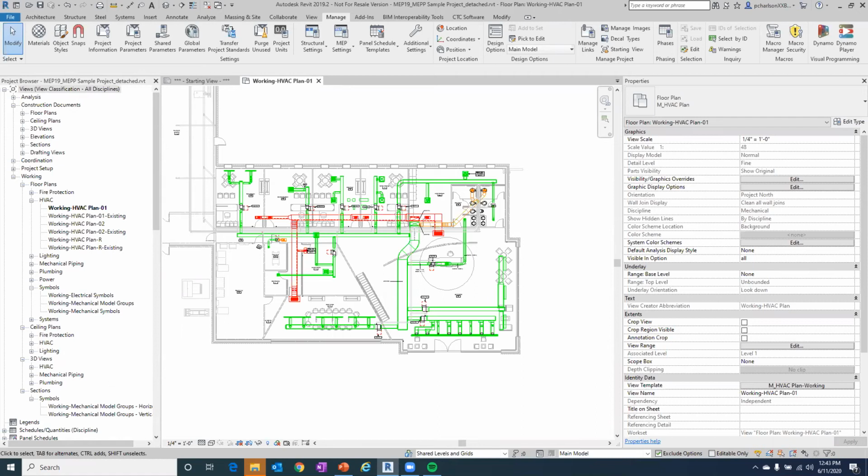Well, we do not have a way to protect our content. Simply, you have to trust, and that's the way it's always been with Revit. There's been nothing for locking down information. If you are sending information out to another company, I would recommend using your purge tool. Go to Manage, click on Purge Unused to clear a lot of the content that you have not used for your project.